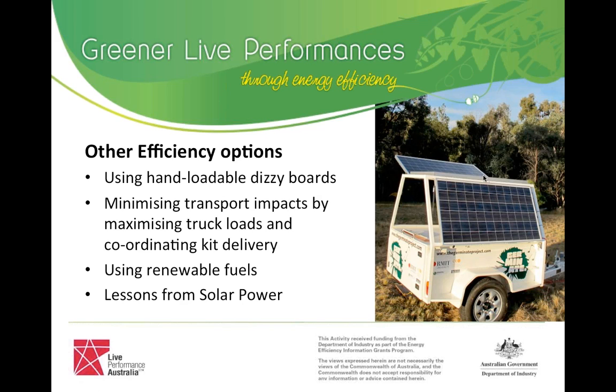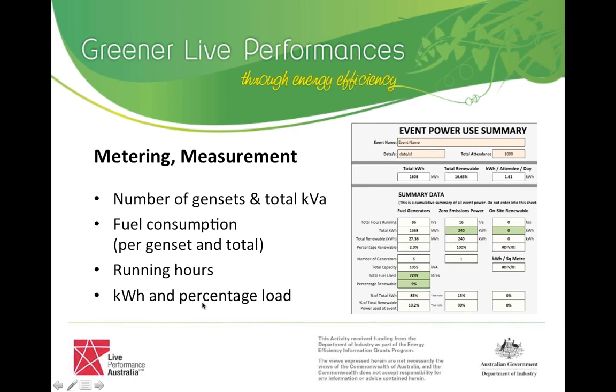If you're choosing between suppliers and you've got a large number of generators and a big amount of distribution, get down into that detail as well and have a look at what that means. So we've talked a bit about actually knowing what your energy efficiency is, and that obviously comes down to measuring. And so we're going to talk about measuring generator fuel consumption in kilowatt hours and trying to come up with an actual efficiency rating.